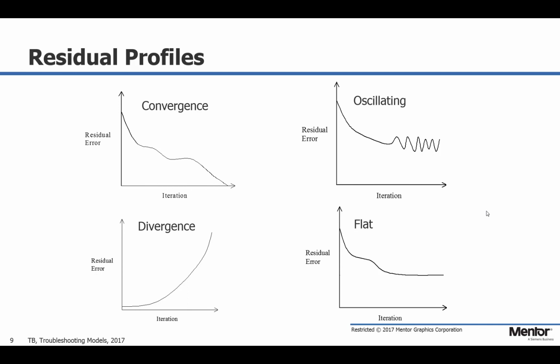This is bad. If you see this, there are a few things to review. Firstly, check your sanity check message window. Inspect the warnings and make sure you understand each one. Next, check all your inputs such as power, fan curves, or material properties. Make sure that's all properly done. After that, you want to double check and make sure you have some basic grid, not just your key point grid. And once you found your mistake, make sure to reinitialize and solve again. Don't just hit solve.